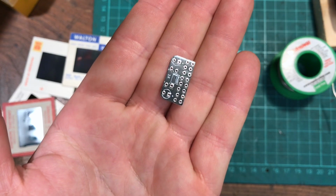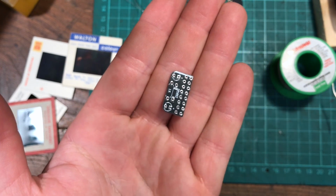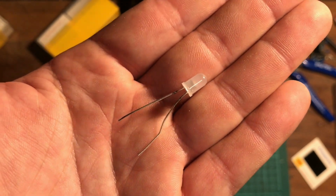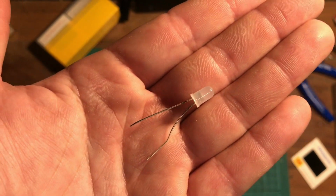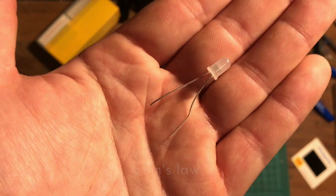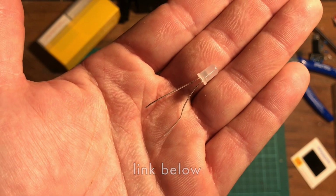Alright, it's looking pretty good. These little LED panels are pretty easy to solder together. They've just got a resistor to limit the current so that the LED doesn't blow up. Now, you're going to want these LEDs to be as bright as possible, so you're going to have to check out how much current they can take. You can find that in the datasheet, and from that you can work out the resistor that you should put in the LED board.